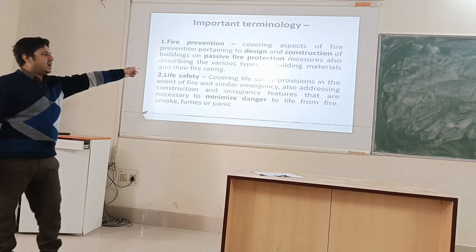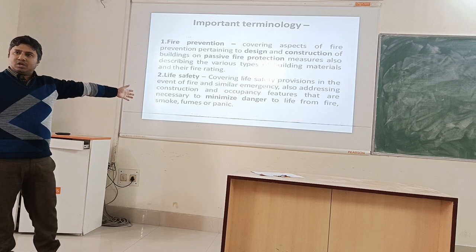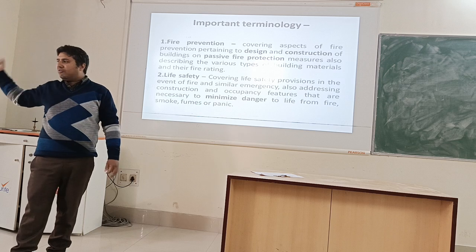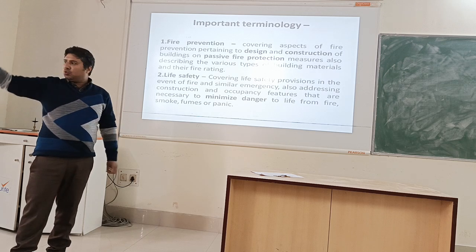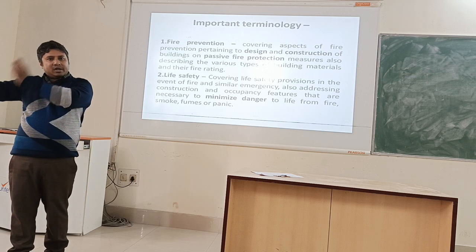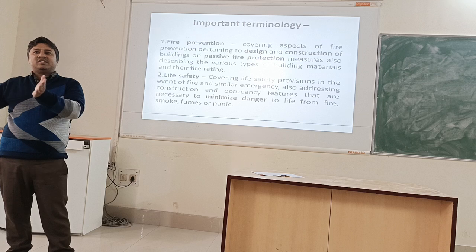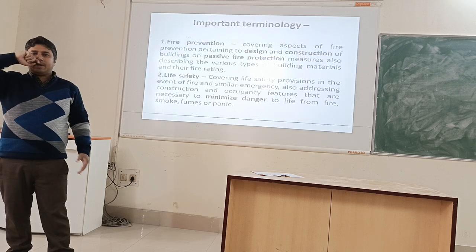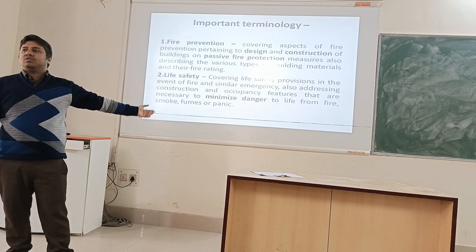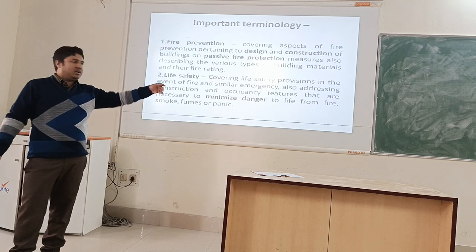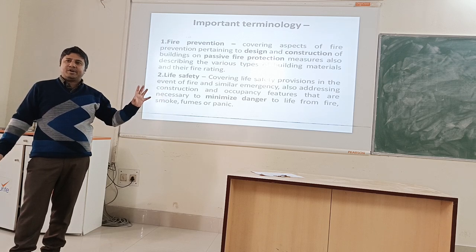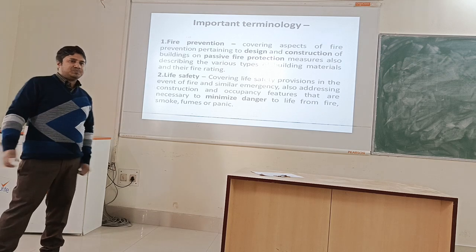If my fire hydrant position is in the front of the building, or mostly it is in the back. If it is in the back of the building, there should be provision for the firefighting truck to come to the rear of the building. So your setback distance should be such that there is room for the firefighting truck to come. Otherwise, you have to make sure that your fire hydrants are placed at the front, where the firefighting truck can come and provide the quantity of water that is required for firefighting in the building.